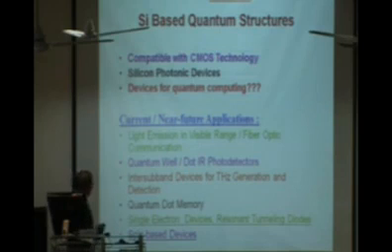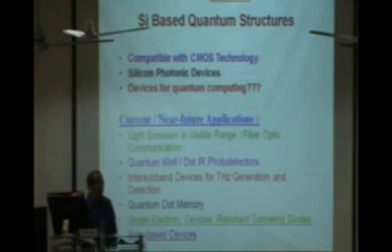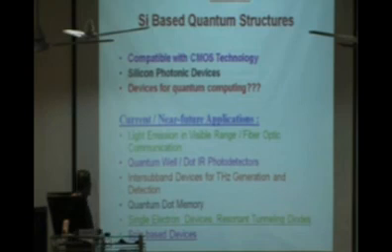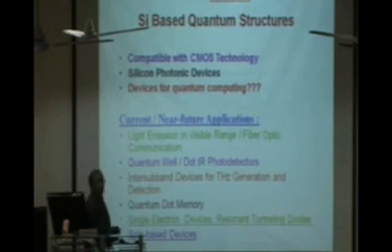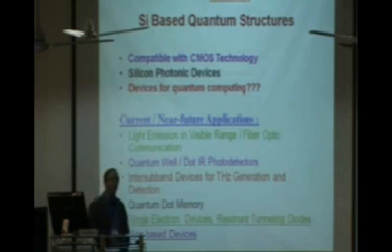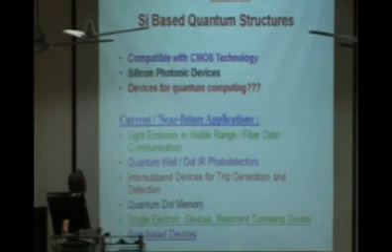Of course, electronically, this quantum dot can act as a memory, which is called a nanoelectronic memory or single electron memory. That is possible. And other things which people have done with a lot of advancement in electron beam lithography are single electron devices, resonant tunneling diodes, and spin-based devices. I have underlined them because these are some of the candidates, we can say semiconductor-based candidates, for probably future quantum computing components or systems. So these are still possible.